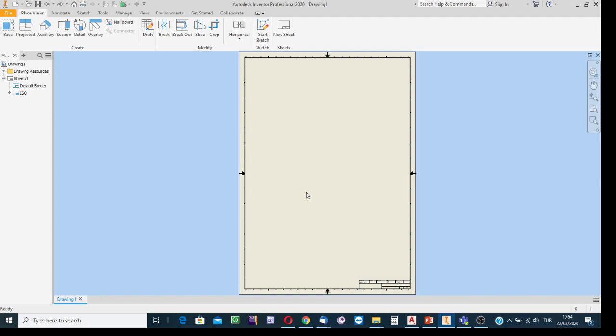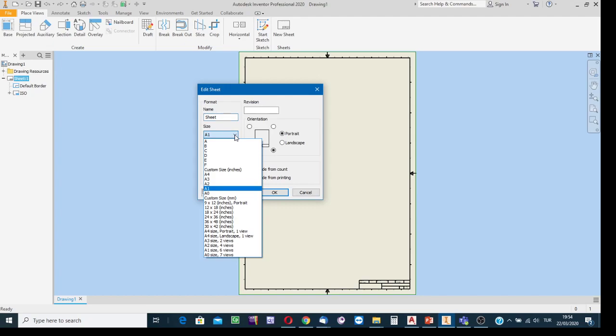Well, imagine that we have, for instance, 10 A0 size papers, connected to each other. It is possible to use papers and correspondingly have paper simulations bigger than A0. See how in Inventor. It is again an editing issue. Bring the cursor to the sheet in the browser, and on the sheet icon, right click the mouse and edit sheet. Well, instead of selecting a standard paper size from this list, select the custom size option.